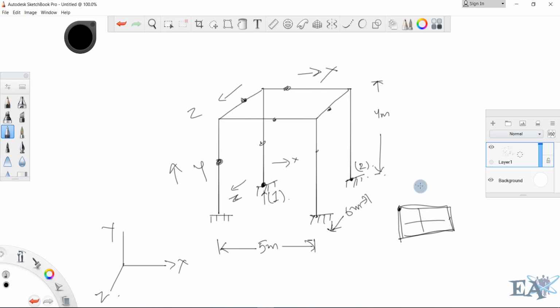Let us assume that all these beams, this 1, 2, 3 and 4, these all 4 beams have got a wall. This is our wall, okay, and let us assume that the load due to this wall is a UDL. If this is a beam, is a UDL, and let us assume that the intensity of this load is 10 kilonewton per meter.